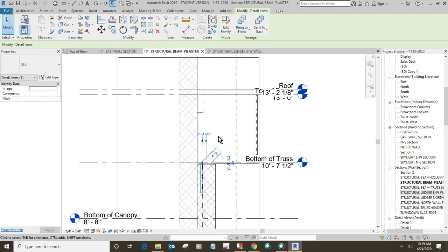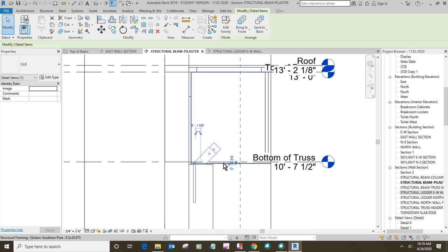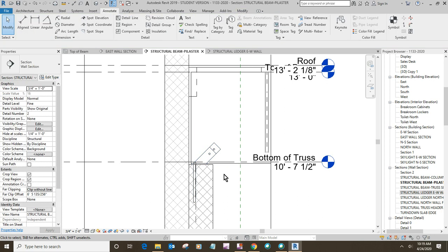and then open it in AutoCAD. So open AutoCAD and then open that file into AutoCAD and see if you need to do any edits to it, because there might be text involved, there might be dimensions, there might be an actual beam drawn in there, there might be a concrete wall here. And so clean it up and delete out all the extra stuff first. Save it back as a DWG file. Okay, and then in Revit,